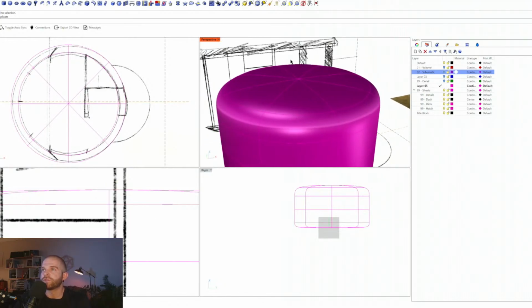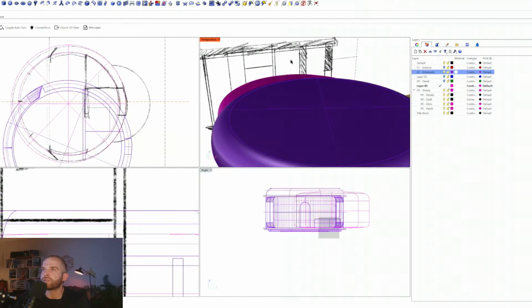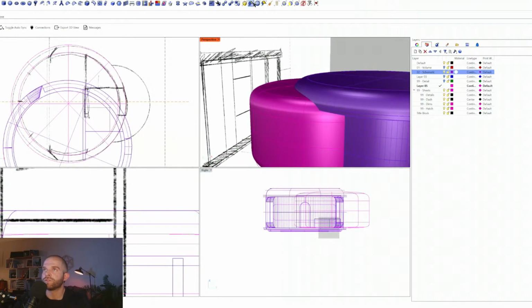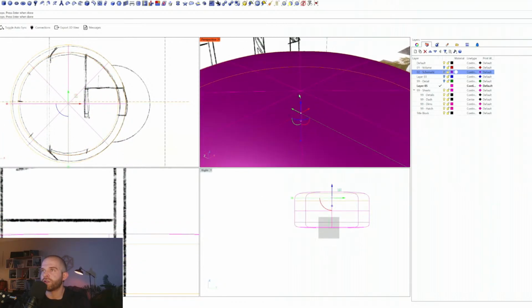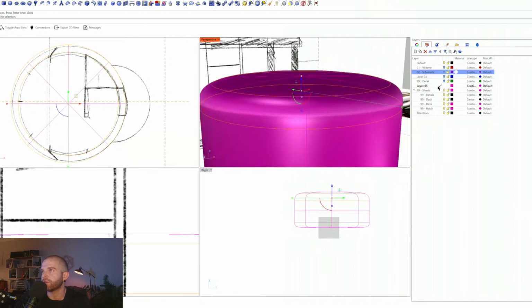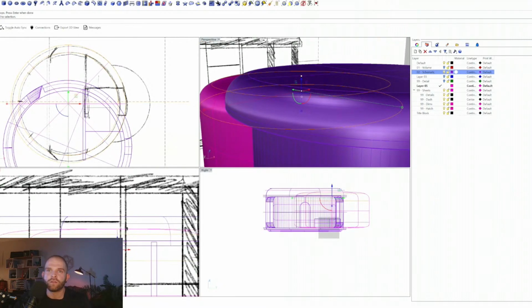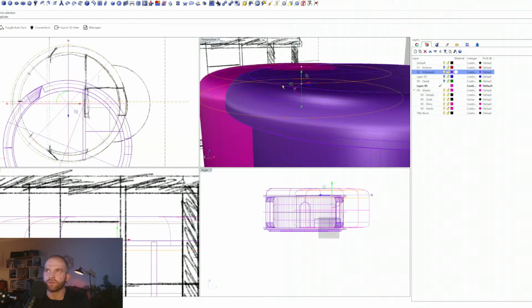I suppose I could show if I wanted to select something besides the edge loops. If I do the edge loop selection again, I'll show this loop, enter. I can also hold Control Shift and add in elements to my selection. So if I click here with Control Shift, boom, there we go. I selected that vertex, that little point right there. And now we can move it all together so that vertex is the one that ends up at top.